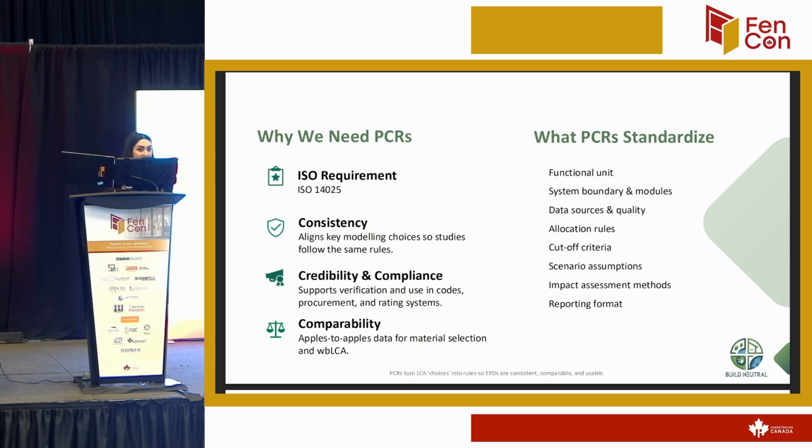So why do we need PCRs? It's an ISO requirement based on ISO 14025. If you want to develop EPDs, we must have PCRs. And it gives us consistency in order to compare EPDs when they are based on the same PCR. It brings credibility, compliance and consistency. And when we are in those PCR working groups, we have to standardize the functional unit, system boundary and modules, data sources and quality of our data.